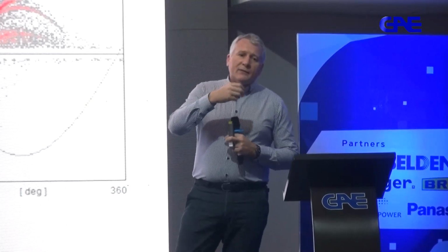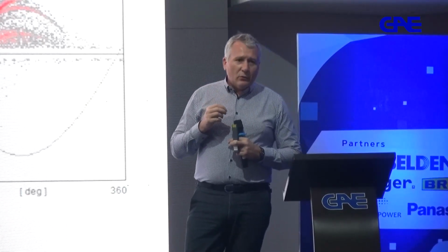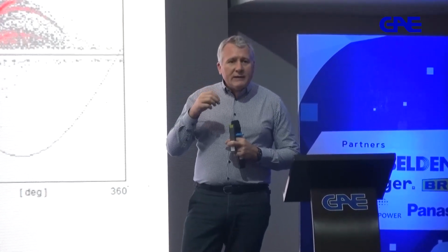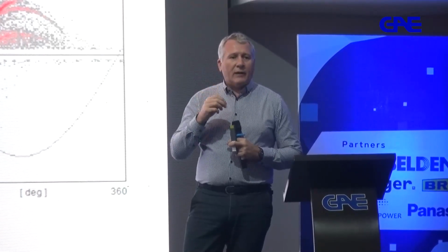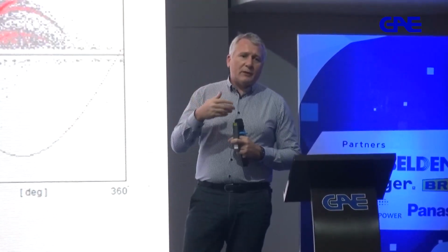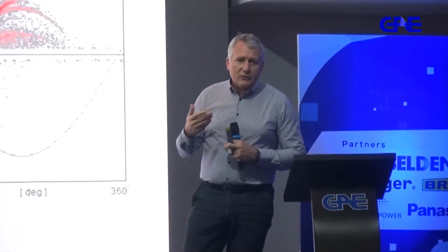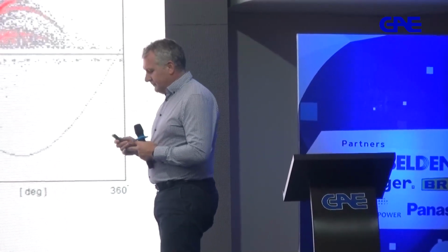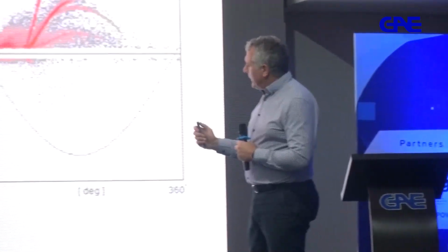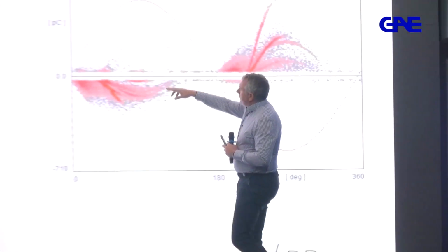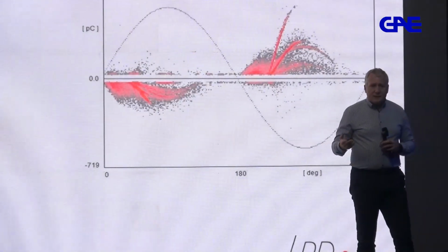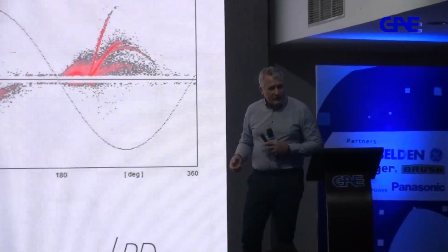So, when you have this charge, this impulse that I mentioned to you, ultimately a device can basically pinpoint where this transfer of electrons happened in phase, and in phase of what? In relationship to the phase of the AC voltage. So what you see on this diagram, I will show you. You can see the voltage that goes through its normal cycles, 50, 60 hertz, depending on the country, depending on the region.